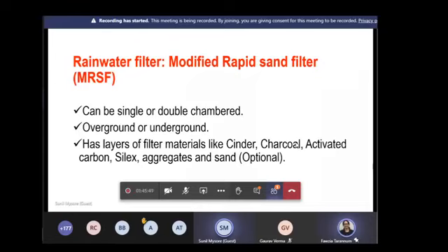Sometimes I use sand, most times I don't. Then I use silex, in different gradings: 20 mm, 40 mm, and 10 mm. Then I use activated carbon, technical name IV900. Then I use cinder. All of these are filter material. Essentially, all of them have got pores and certain chemical properties which can filter the water. And provision can be given to clean the filter, because the filter also gets clogged, so you need to keep cleaning it once in a while.